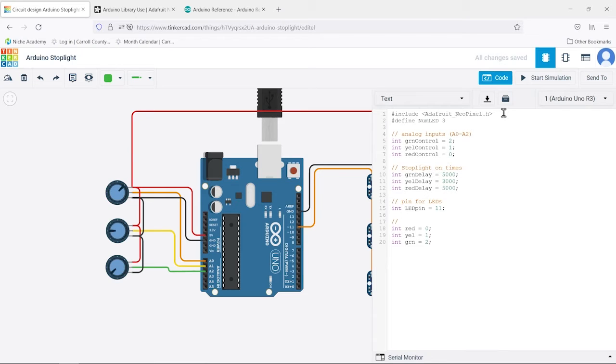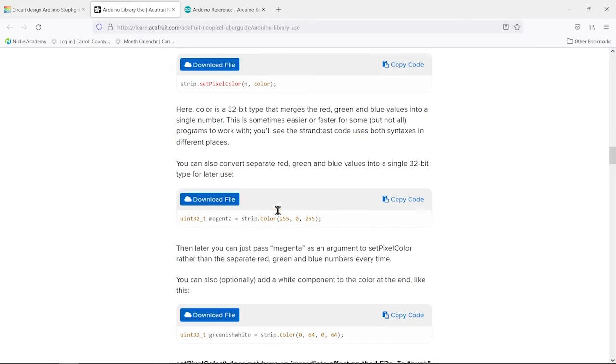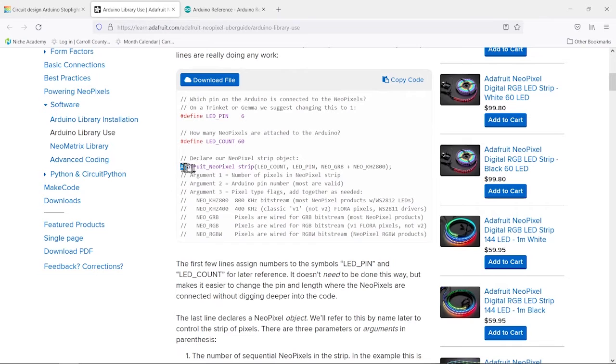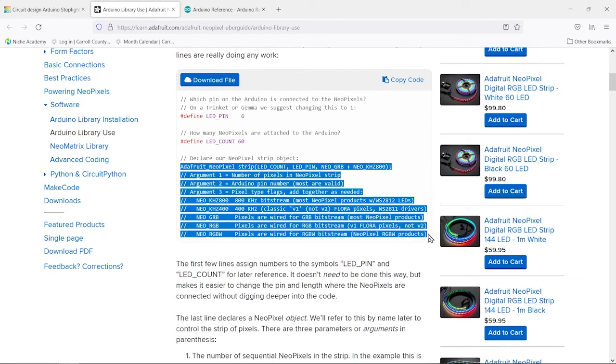The Arduino platform is based on the C++ language, and as such is referred to as an object-oriented language, albeit with some limitations since the code runs on a microcontroller as opposed to a computer. What this means is that data and functions are organized into objects as opposed to separate elements of code. Think of objects as a container that houses all of the logic and data for a specific process. In our case, we're going to initialize an object that is responsible for controlling the array of Neopixels. Let's take a look at the library documentation to see exactly how to initialize the object as well as the properties of that object we'll be able to access.